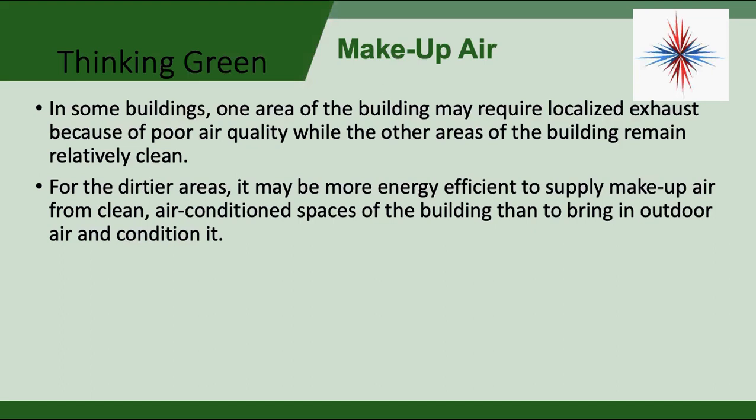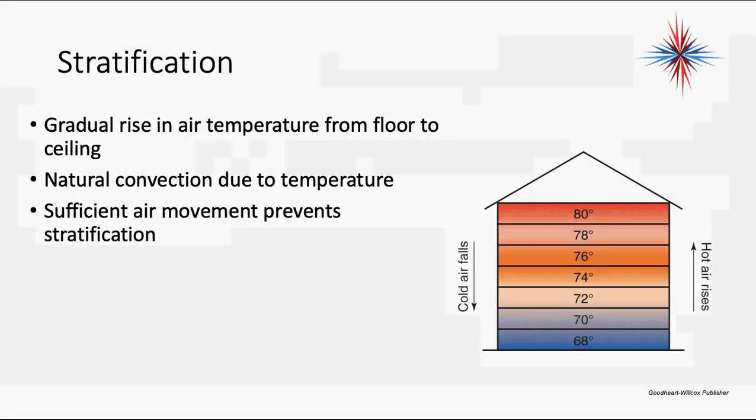We started putting commercial kitchens into residential construction, and these pulled a lot of air out of the house. You turned on an exhaust fan in one of these, and the entire house went into a negative pressure within about 4 minutes. People's fireplaces were venting backwards into the house, so they suddenly needed a lot of makeup air. Makeup air is when we bring in outdoor air or inside air from another area of the building.